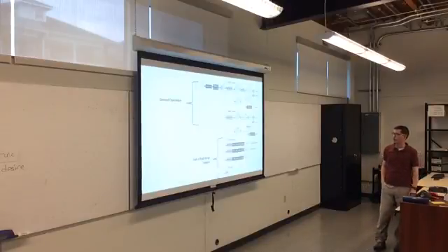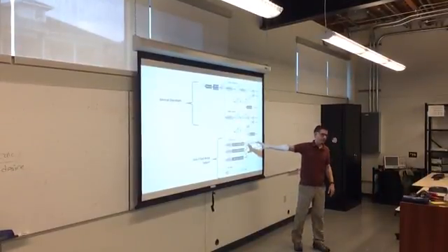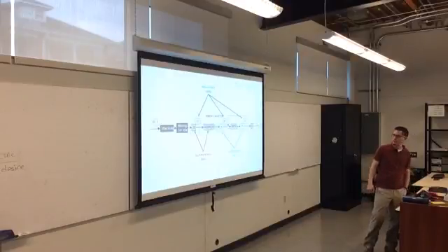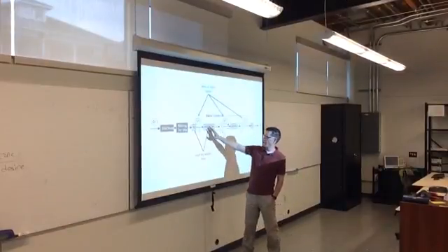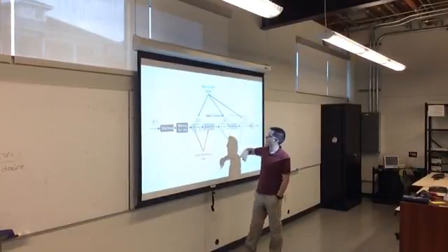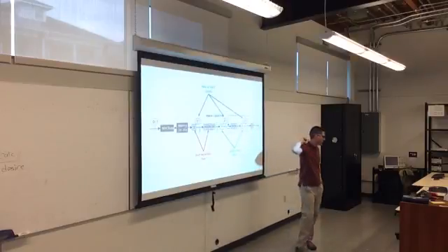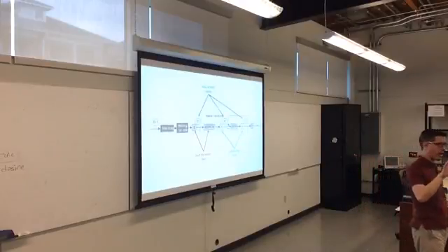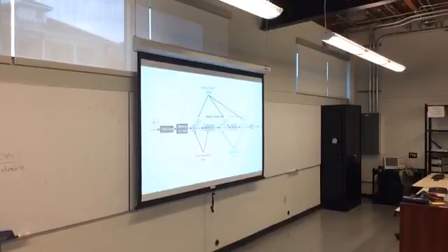And again, the color coding means lighter gray is stuff the master device does. These bubbles are the exact value of the state register. So if you pull up the state register in the registers tab in your IDE, you will see the number 57. And if you see the number 57, that means you have transmitted a start bit. You now need to transmit an address bit with a write, and so on and so on. Those are your different states that you need to do.